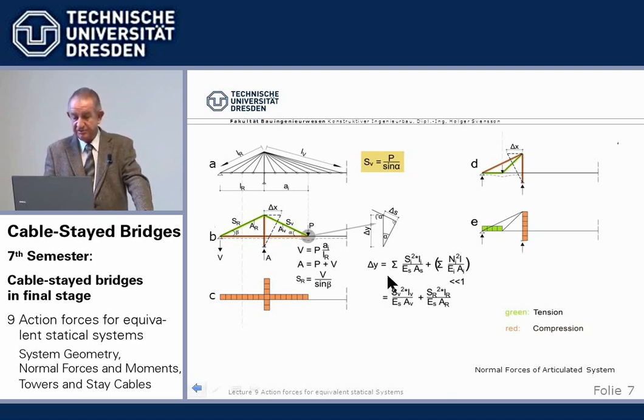Basically, of course, it runs down that we calculate the cable forces for unit load 1. The cable forces here are always trigonometric functions, 1 divided by sine, basically. And then to get the elongation, which we want there, we would divide that by the modulus of elasticity of the steel and the area.